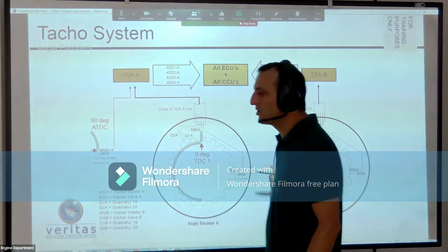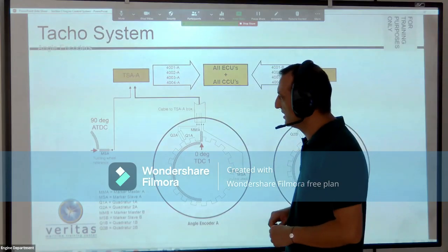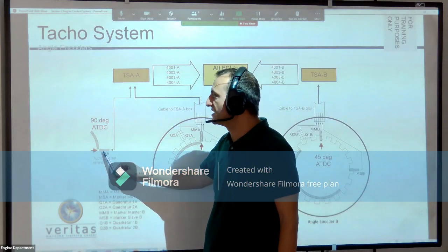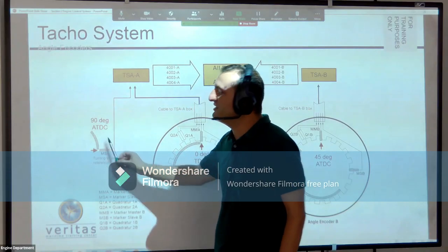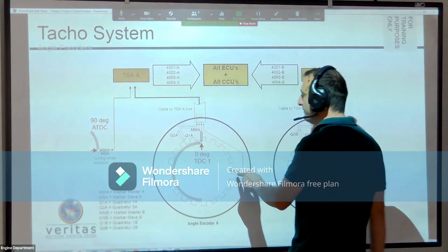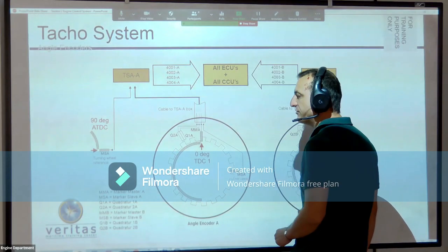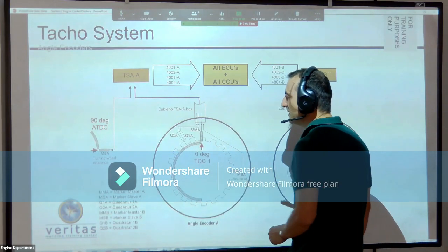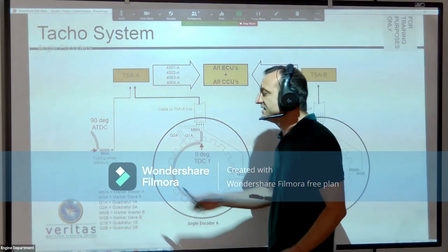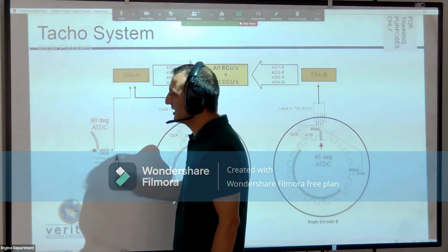Instead of the signal from the marker slave A, we will receive a signal from the flywheel of the engine. The encoders are located at the forward end of the engine. At the flywheel of the engine, we have an inductive sensor which gives the same reading that must be given by the marker slave A from the encoder. So we are using this sensor like a reference sensor.